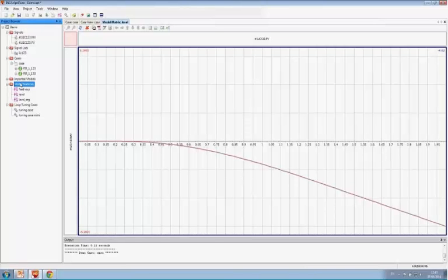A very detailed one. How can I use a measurement of a disturbance signal to improve the model? You said that it's possible, but how? Well, let's say I have a disturbance signal, like outside temperature or something I can measure but can't influence, which is actually influencing my model in my step test.